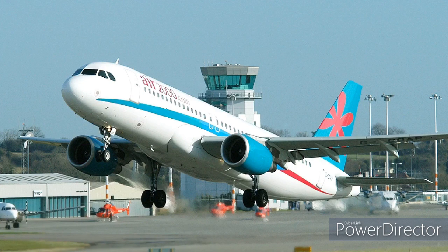There may also be a performance limitation imposed if one engine thrust reverse system is inoperative, as the total reverse capability will be reduced, and on an aircraft with two pod-mounted engines, having one engine thrust reverse system inoperative may mean that the remaining serviceable reverser cannot be operated either, because of the asymmetric effect it would impart upon selection. This concludes the lesson on reverse thrust.